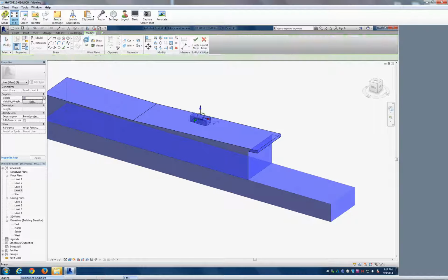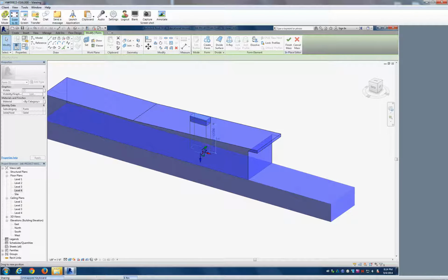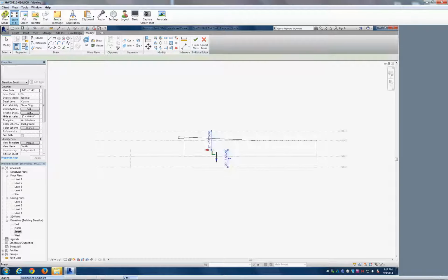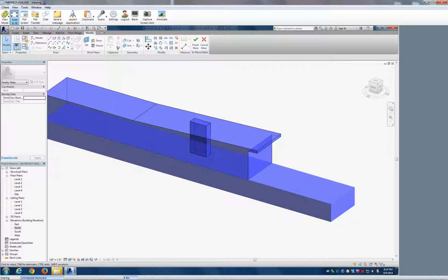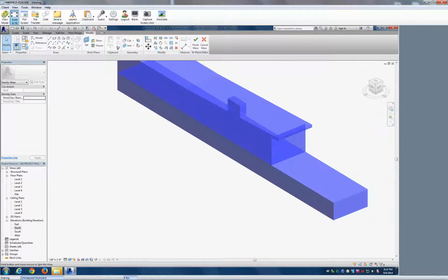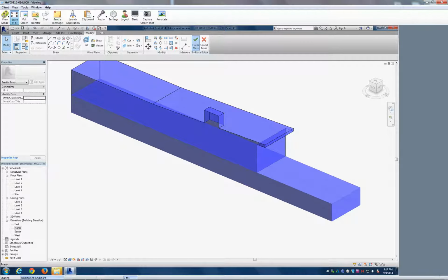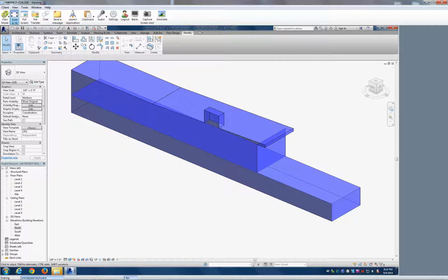So create form. We can just wedge that in there, just bury it in. And then what we'll do is join. Because we opened up that geometry, we can say join that with that. And there it is. Yeah, it makes it one mass. So just think pink foam, you're doing a massing model, okay? Don't worry about too much detail. It's just a mass, all right?